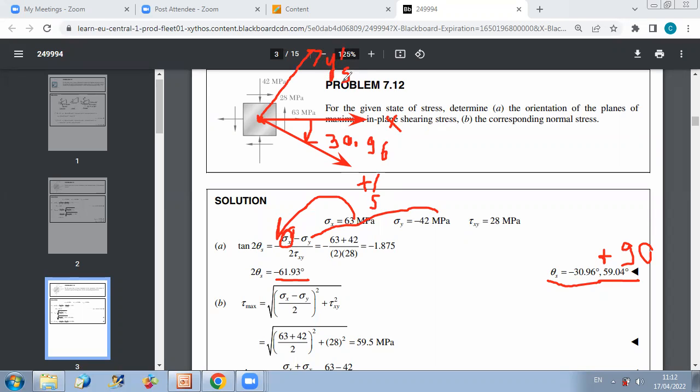And you can deduce from here now the principal axis, because as we mentioned together before, the angle between the maximum shear axis and the maximum normal stress axis is 45 degrees. So if this is x prime s, then x prime p is like this. This is x prime principal, and if I go from this one to this one, I have a total angle of 45 degrees.